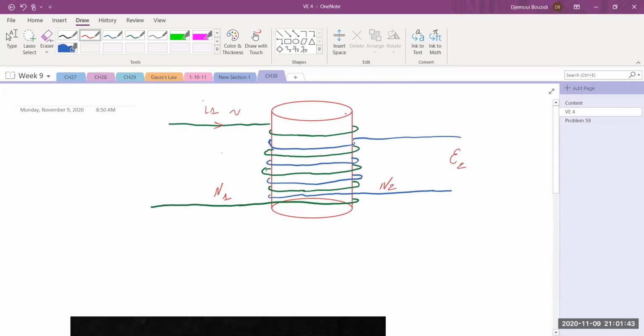This is the picture that I have of the thing that I actually tried to build in here. But as I said, this will not work for 2 reasons. For the first reason, I really need an AC current, an alternating current. That's reason number 1. Reason number 2 is it will not work even if I have like a 20 volt AC current, because I know the current that is going to be generated in there is not strong enough to have a decent magnetic field that is going to have a decent flux that is going to induce an EMF in the second part. Okay, does anybody know what this device is called?